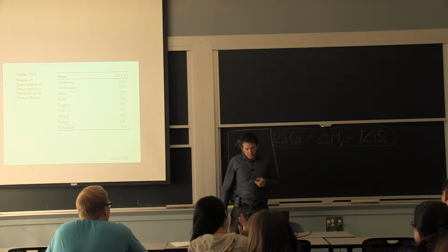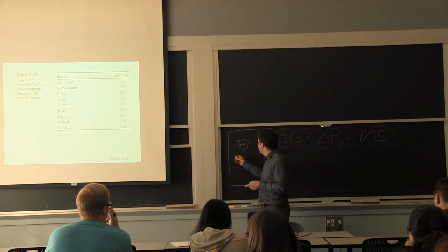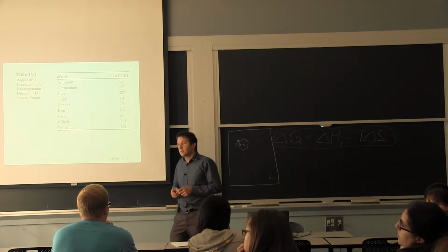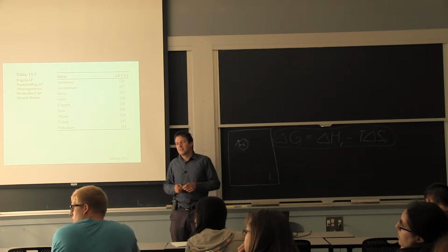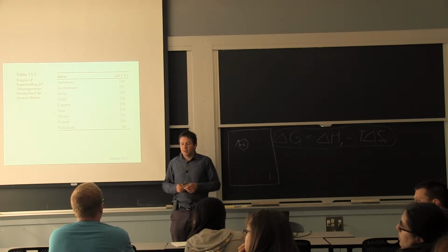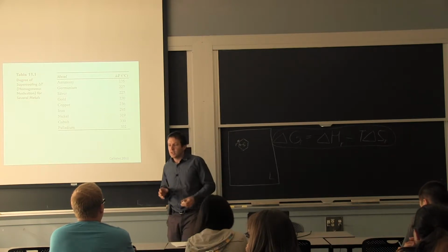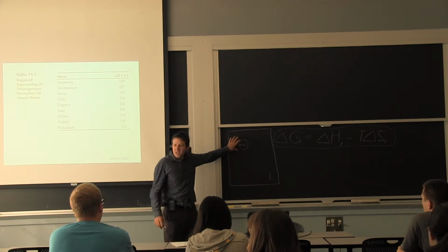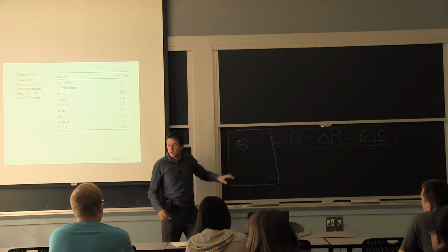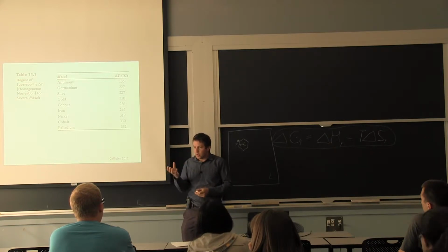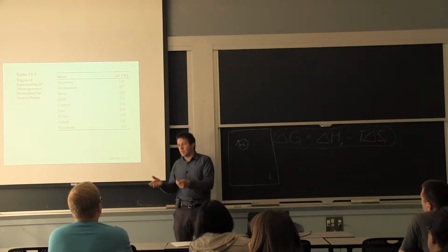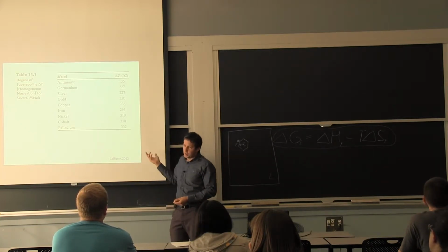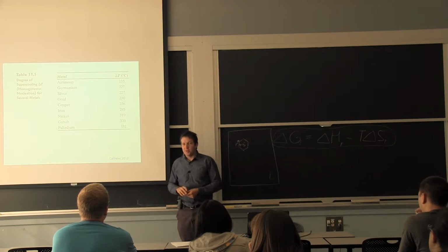So from that temperature, if you're looking at steel, you would only form these crystals about 300 degrees below. Yes? I know that in monocrystalline wafers, they just put a single crystal and show the... Yes, yes. So if you have something to begin with, and that's my next slide, you will essentially eliminate the need of forming it in the first place. So by the time that you have something to start your crystal, and it doesn't have to be necessarily another crystal, it can be an impurity as well, you're reducing this, and you can reduce it to pretty much 1 degree or 10 degrees, depending on the temperature that you're dealing at.